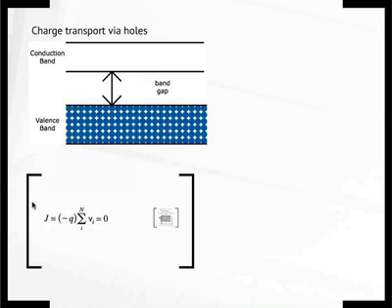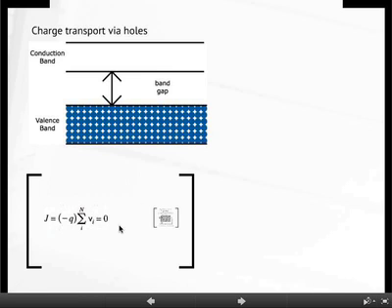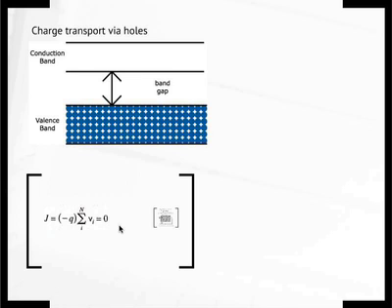In principle, this is current density, because N is typically in per unit volume. Now, this is 0 primarily because if you look at the band diagram of the valence band, which is K, remember K is proportional to velocity. If I pick a certain energy level here, I have one value here, which is K. I have an equal and opposite value here, which is minus K. Okay, remember, we're only talking about valence band now.